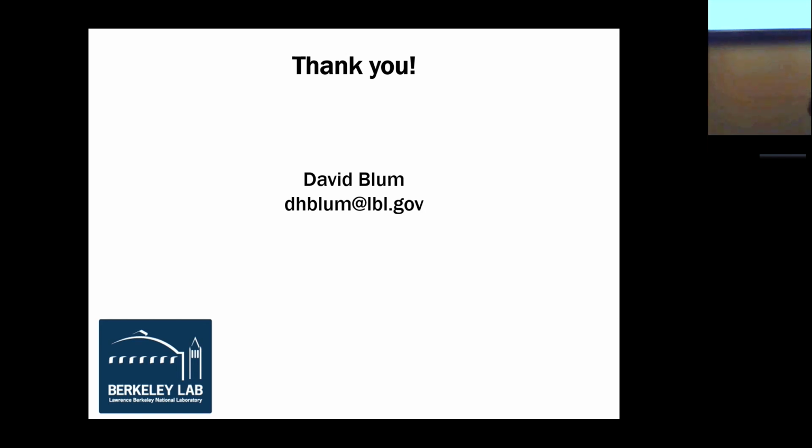Yeah, so that's a good question too. The question was about whether there's data available to train models for MPC load prediction or other controllers like that. I'm trying to think. The emulators that we have available basically come with TMY weather data. The reason I start with TMY weather data is because it's usually 1 year's worth of data. So what we have right now in our emulators is 1 year's worth of weather data available. So you can run the simulation anytime during that 1 year period.